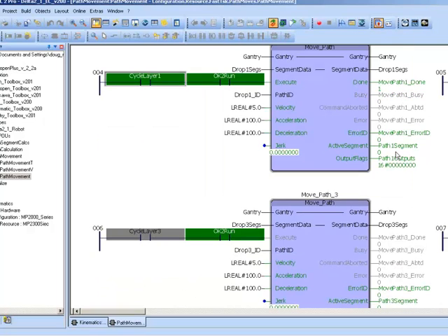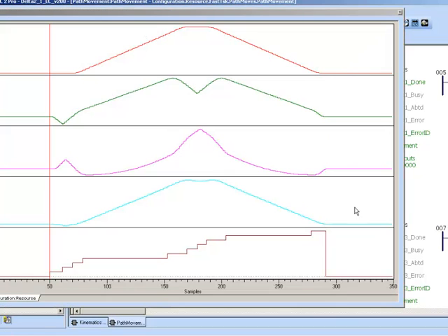You may not have seen that show up on your screen, so for your benefit I took a logic analyzer trace, and what this pop-up shows here is our virtual Z position as the second line down in green. The virtual X is in our upper position. So you see that the mechanism went down in Z, picked up a part, then it moved diagonally to a drop-off point, and then it went and dropped it off straight down and back up again, and then it moved back to our hover point.